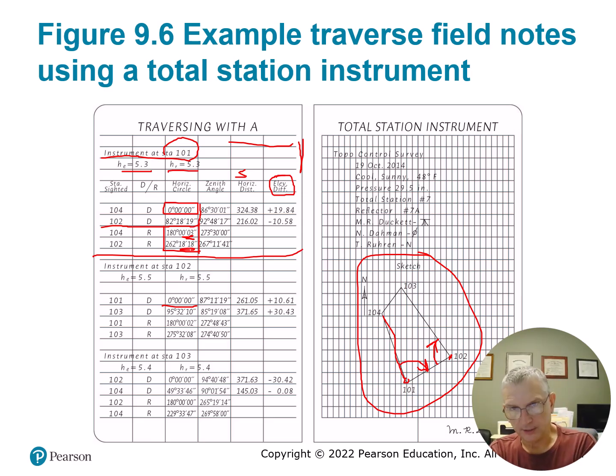Now for simplicity, we're just going to turn single angles and process those, but this is one method of multiple observations on a point, which is to back sight with 0, turn your forward angle, then you reverse with 180, and you turn your angle right in the reverse mode. And here you'll see your zenith angles are inverted. So again, there's a lot of different formats, but that's what we're doing, is we're collecting the interior angle. Typically might be the exterior angle of this shape.